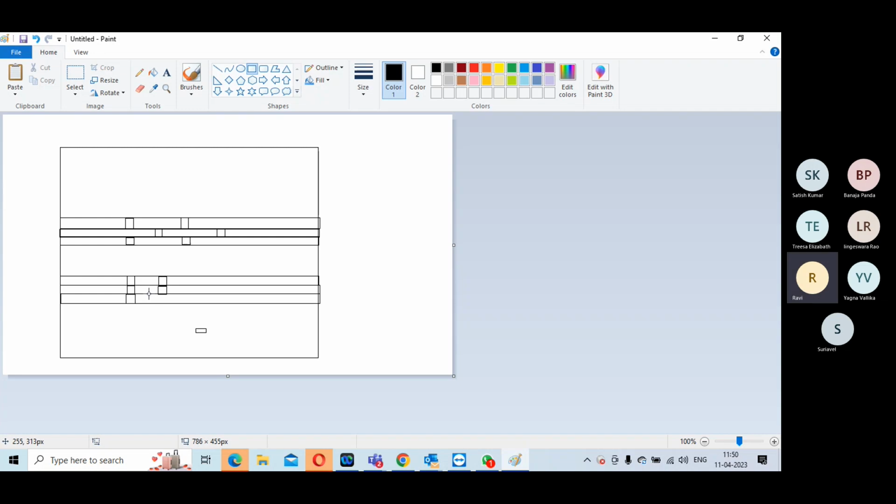Your latch up requirement: within 50 micron of that particular cell, you need a hole to connect to the substrate so that the latch up issue will not exist. Now, how do we decide that we need 50 micron?